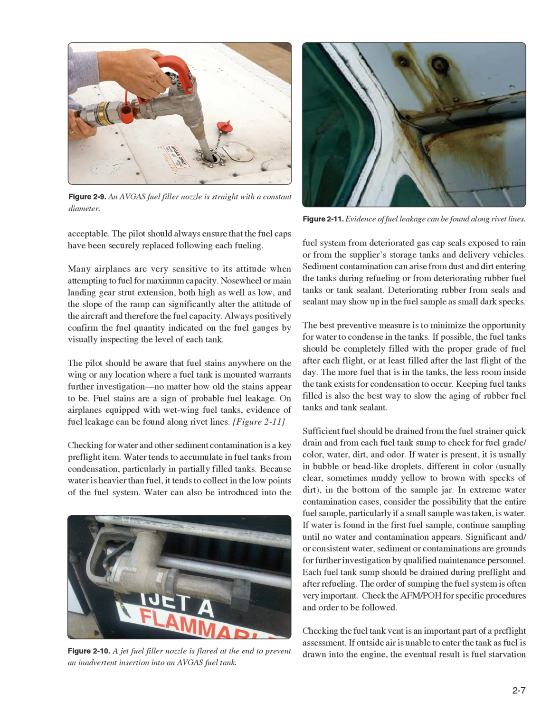In extreme water contamination cases, consider the possibility that the entire fuel sample, particularly if a small sample was taken, is water. If water is found in the first fuel sample, continue sampling until no water and contamination appears. Significant and/or consistent water, sediment, or contamination are grounds for further investigation by qualified maintenance personnel.